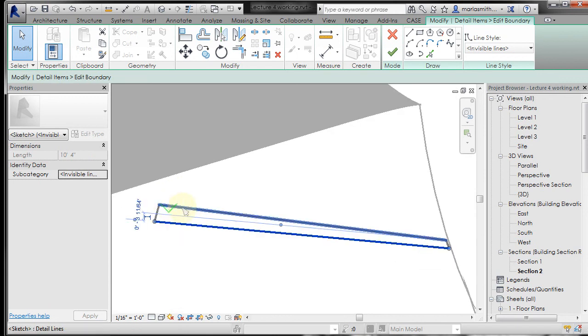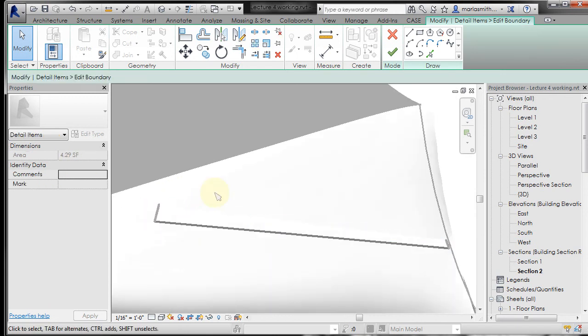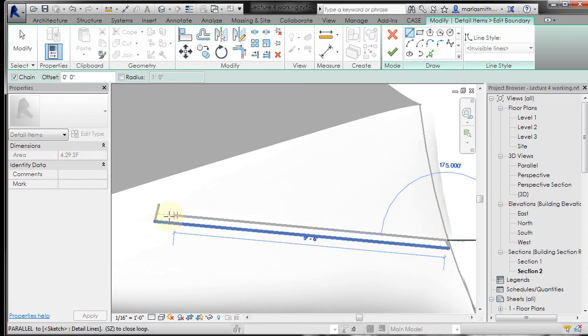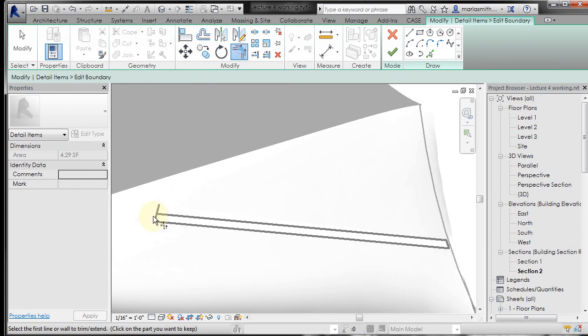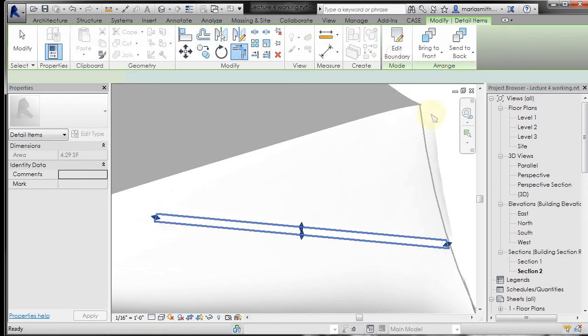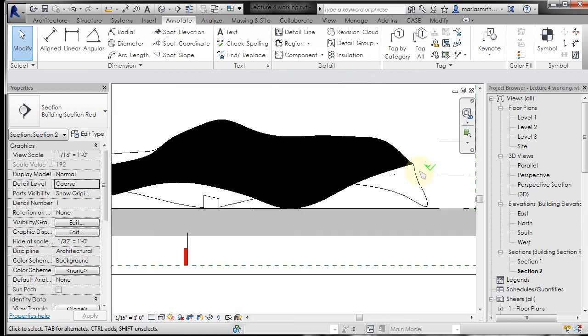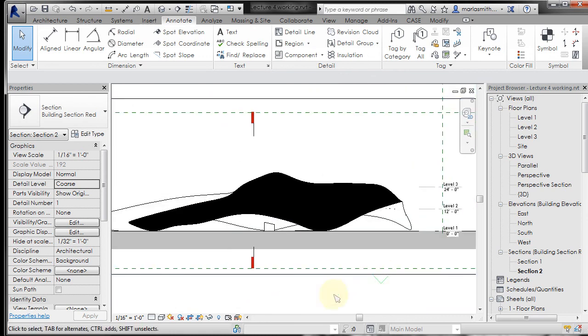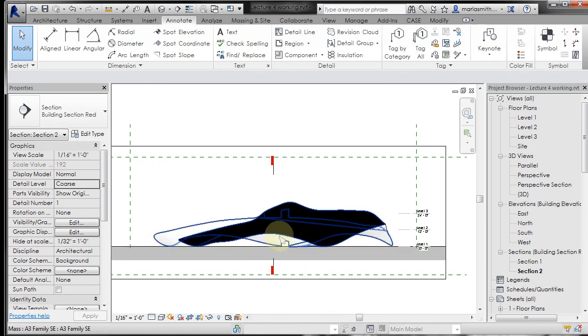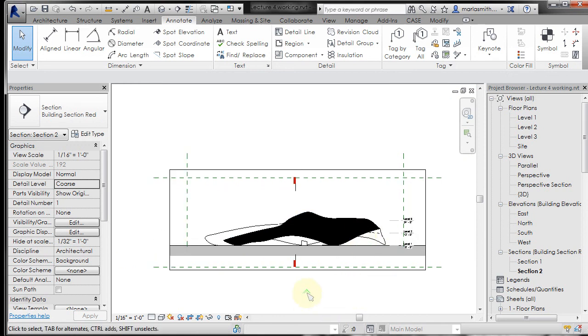Or maybe just delete it and create another line that's a little bit more closely related to that. And this has to be fully closed, can't have any overhanging, so I'm trimming that. So it's a little less obvious, right? But you're going to get a little line there and maybe you can live with that. But it'll give you sort of a nice shade underneath that. Okay, so that's another option.